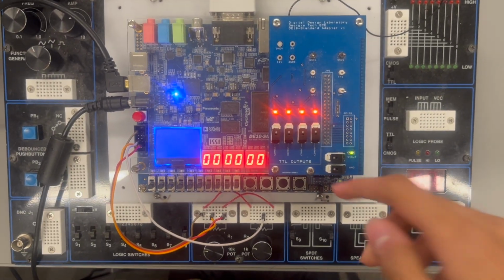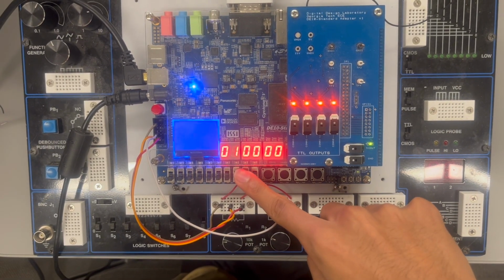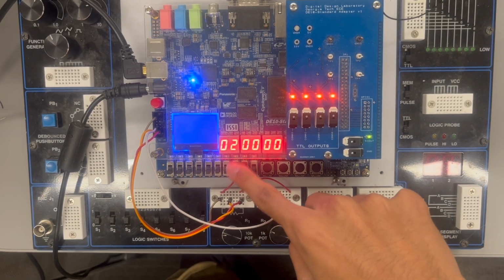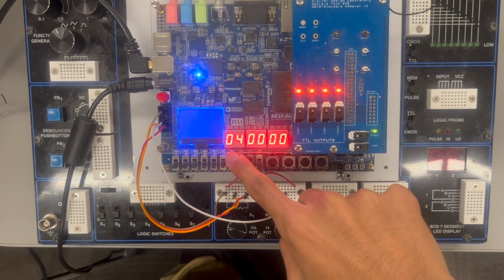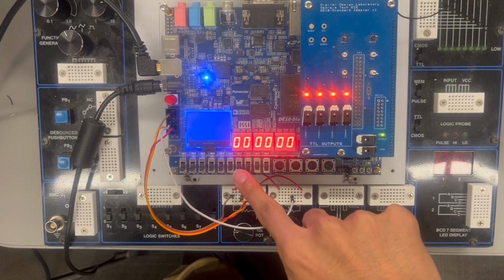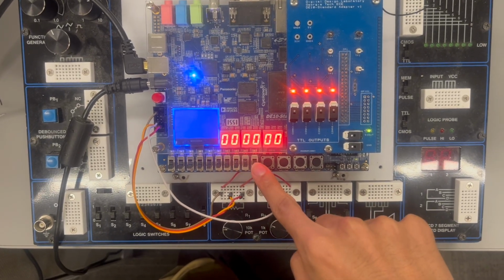Now let's go through the actual application and its interaction with the ADC peripheral. As we said earlier, we can select the channels using the control register and view them using the status register. Here we can see we're choosing the registers displayed on the Hex 1 display. We have a total of 8 registers, but we can see that currently only registers 0 and 1 are attached to the potentiometers, 0 to the left dial and 1 to the right.